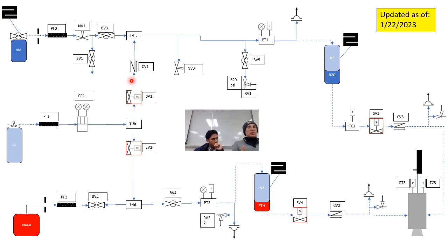We want to verify as soon as those are flowing in, we expect combustion to begin: a rapid increase in pressure in the combustion engine, thrust starts being measured. If any of those things are not measured very quickly, in a fraction of a second, that means we're just flooding our engine. So we want to immediately shut down the test. So that's where the abort system comes in. So we'd be looking for some of those things.